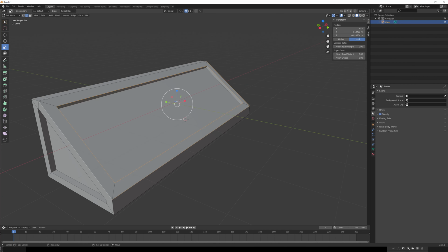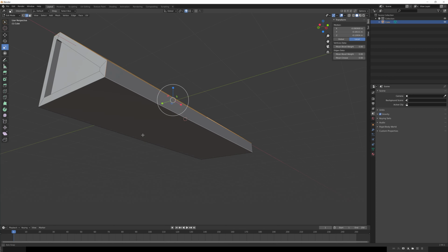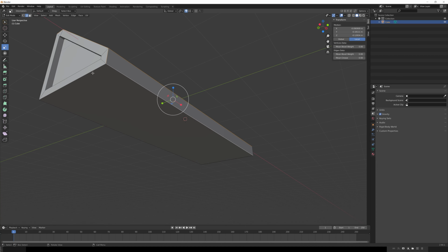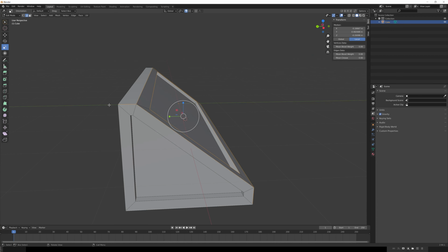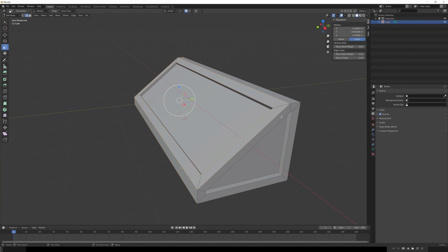So why don't we go ahead and grab all the way around some of these different edges. The thing with beveling is that you do have to be careful about which edges you select. And you also should think about whether or not those edges will ever be visible. Selecting the back side of these means I'm going to round that back edge. Since I think that these are always going to be pushed against a wall or some other location, that really doesn't help me out. And I'm going to go ahead and select these parts over here too.